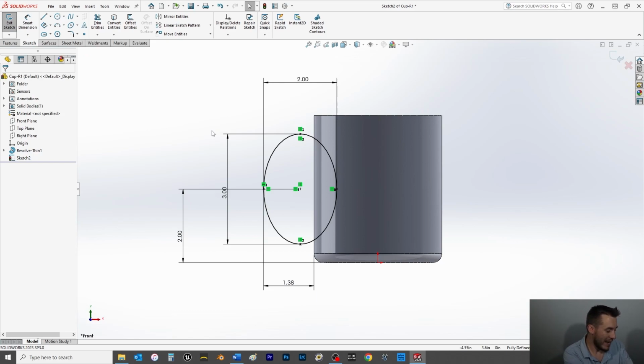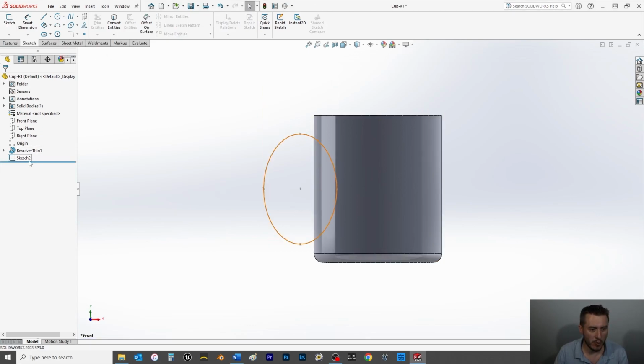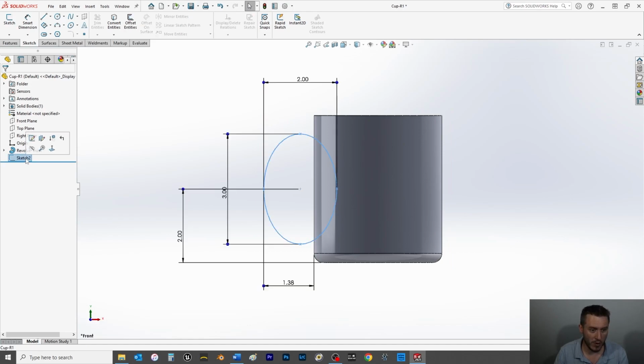So we're now at the middle of page 252, section 8.4. We are not going to start into the feature quite yet. We are going to create an auxiliary plane. So to do so, let's first exit the sketch. We'll come over here in the feature tree, click once on Sketch 2, click twice, and then we will rename it Path Sketch. Hit enter, Control S. Save often.